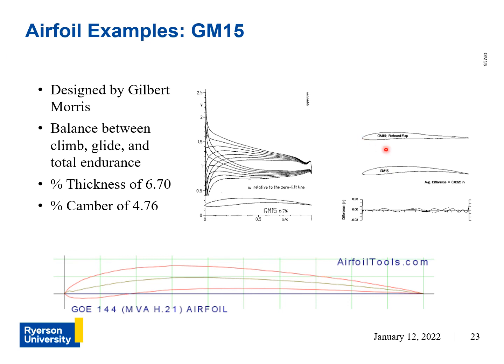So basically, during the climb phase, the camber is decreased because the airfoil becomes reflexed. So it has a reflexed configuration here, as you can see. And during the glide phase, it has an unflapped configuration, which means that the camber is high and it will look like this.